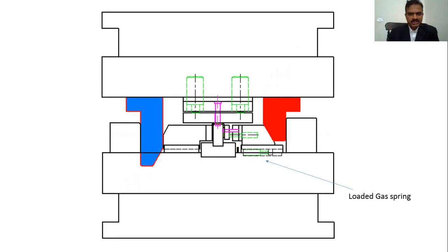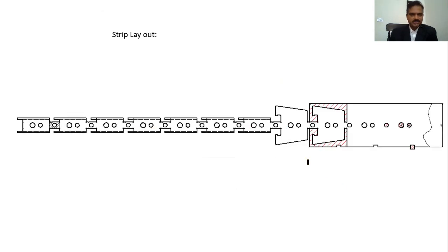It is now both drivers are shaded for better comprehension, and this in the bottommost condition, this is how the part will be processed in that particular station. So this is a key point here, and now the driver is going to push the cam forward and initiate the cut, and somebody has to take this cam back once the driver goes up, right? So you can observe here there is a gas spring, and this gas spring is going to push the slide back into position, and it's on either side too.